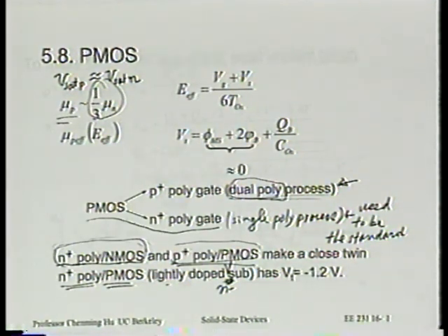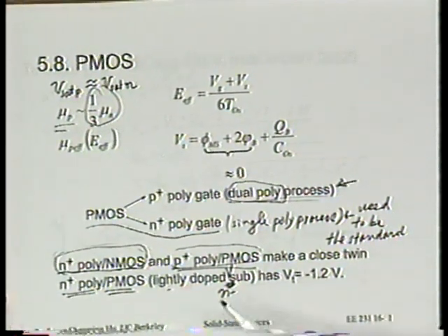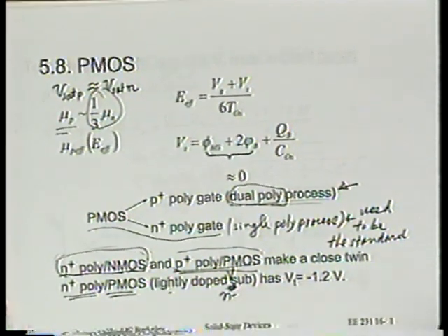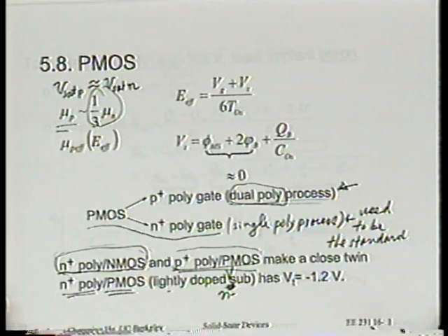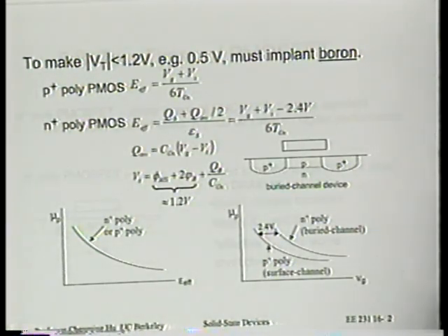It's even farther from what you want. All right? So therefore, for this 3rd kind of transistor, we do something special. We actually implant counter-dope the substrate. It's a very unusual approach, all right? We would put boron into this N-type substrate in order to bring the threshold voltage down to a low enough voltage.